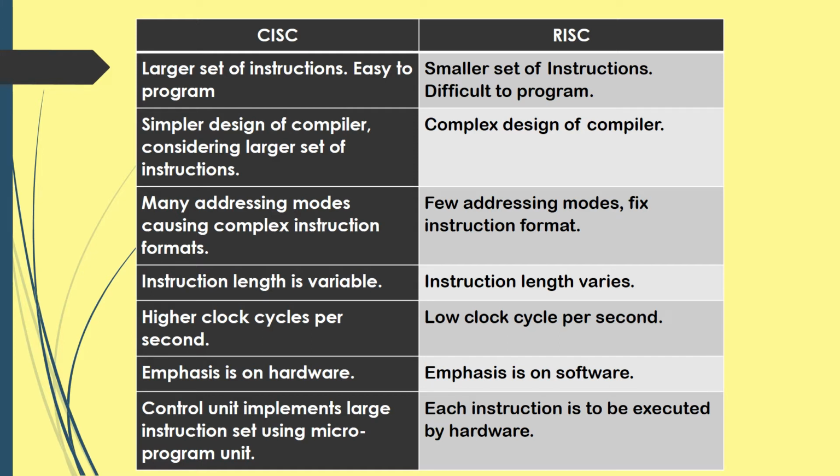The architecture called CISC is the architecture that attempts to minimize the number of instructions per program, and it sacrifices to a certain extent in terms of the number of cycles. The reduced instruction set architecture is doing exactly the opposite, reducing the cycles per instruction at the cost of the number of instructions per program.